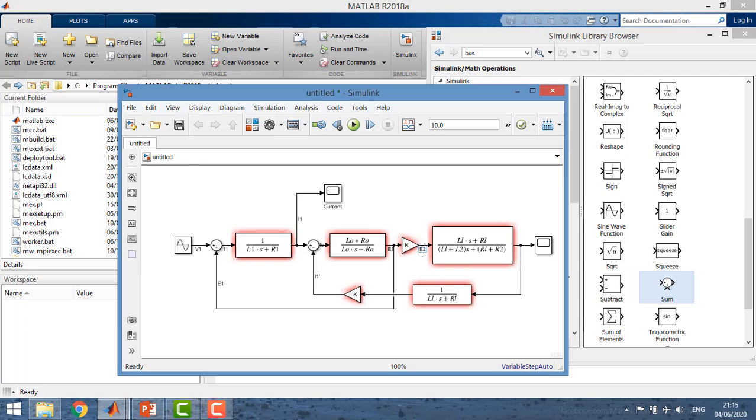So multiply the induced EMF in the secondary winding with this transfer function to find the secondary winding voltage, and simply divide the secondary winding voltage by the applied load to find the current in the secondary winding, which is transferred back to the primary winding by multiplying it by the turn ratio. Again, we are trying to extract the primary current and secondary voltage.